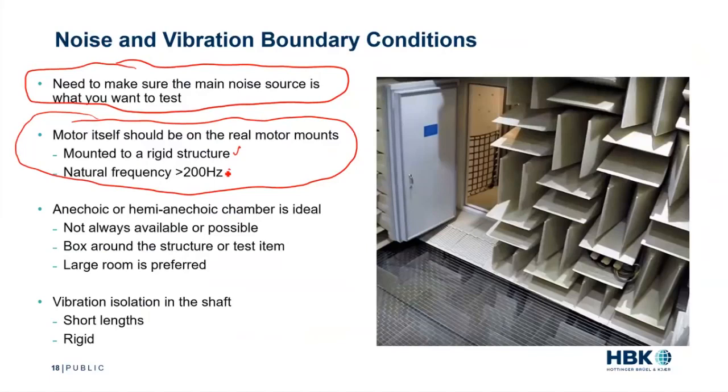The fun part comes when we start putting our machines in an anechoic or hemi-anechoic chamber. This is so that we can isolate those noise sources. But we have to consider that there is a shaft that is connecting our device under test to the outside world. So if I have my device under test, DUT, I need to have a shaft going to the outside world because I want my load machine to be outside in the other room. And this creates some interesting scenarios.